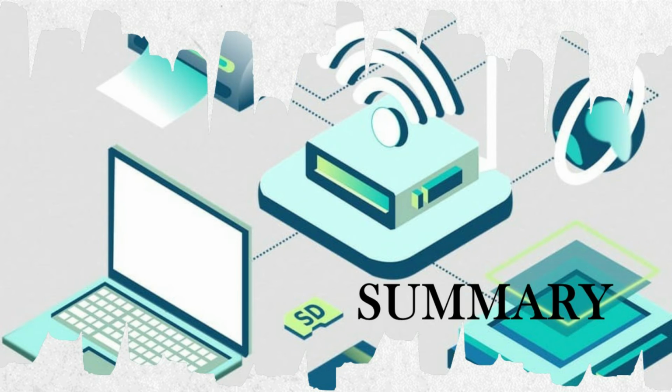Sixth point. Cabled networks typically use one of two transmission schemes, broadband or baseband. Broadband transmissions use analog signals to carry multiple channels on a single cable, where one channel is required to send and another to receive signals on most networks. Baseband transmissions use only a single channel to send digital signals that occupy the cable's entire carrying capacity.